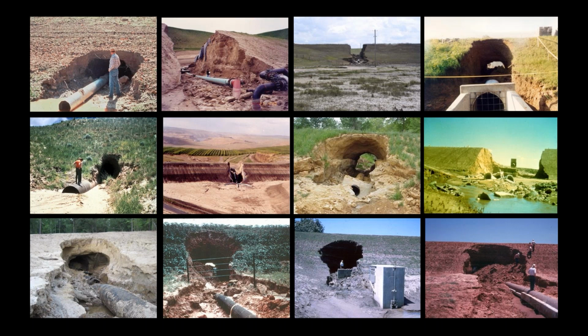What's common about all of them is that they failed where there's a penetration through the embankment. So if you're inspecting a dam or assessing it, this is probably the place you need to slow down and really look. Is there any seepage coming out from around the exterior of the conduit? Any depressions, sinkholes, or anything like that?